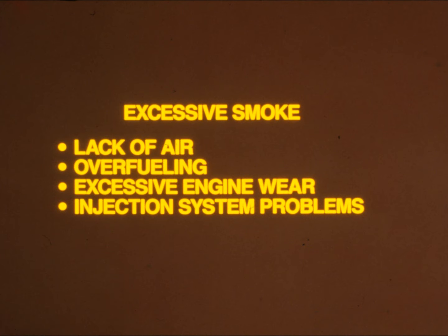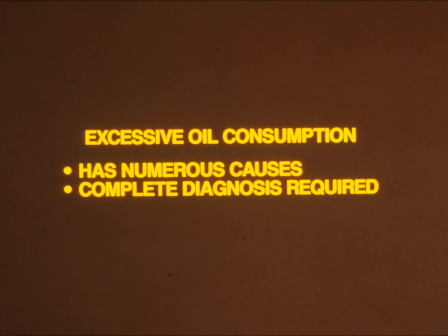Excessive smoke has 4 likely causes: lack of sufficient air to the engine, overfueling of the engine, excessive internal engine wear, or injection system problems. The only cause related to the turbocharger is insufficient air, which can be caused by a plugged air cleaner or restrictions in the intake or exhaust system. Excessive oil consumption can result from numerous causes besides the turbocharger. A complete diagnosis is required to be sure that you have determined the source of the problem.